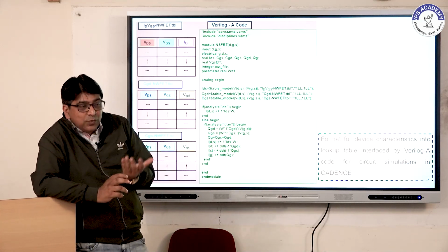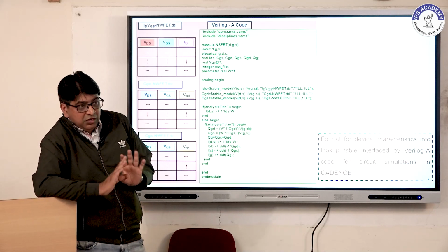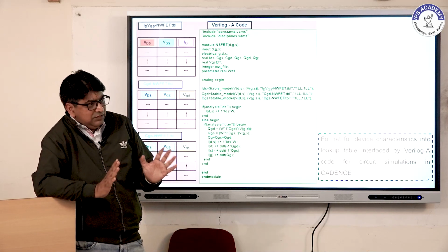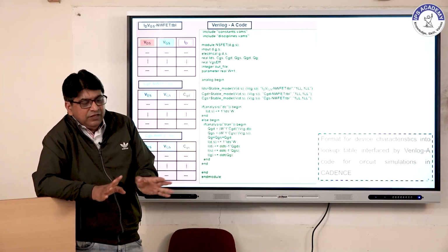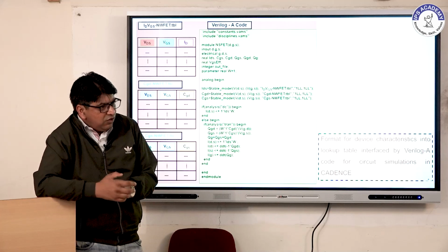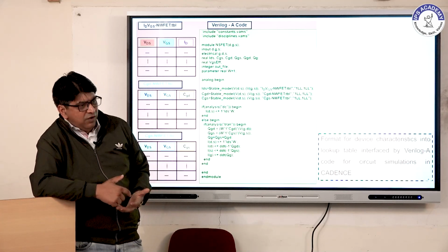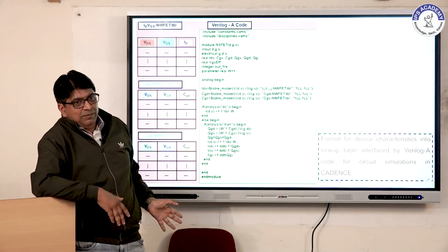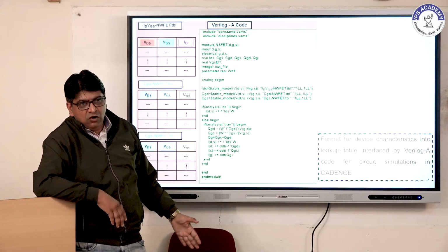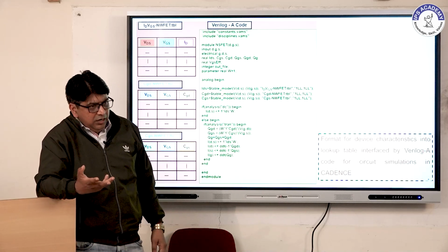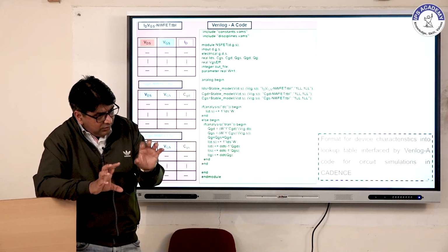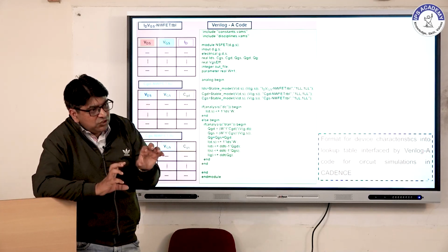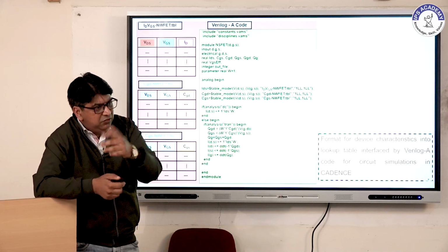Suppose you introduce a high K spacer and confirm that your device is good, with good on current, good off current, less short channel effects, and good RF and analog figures of merit, and you want to check some circuit performance, maybe a digital or analog circuit. You can prepare this table, and with the help of this Verilog model, call the LUT and create the symbol in Cadence. The simulation will be done in the Cadence tool. So we created NMOS and PMOS symbols and do the simulation.